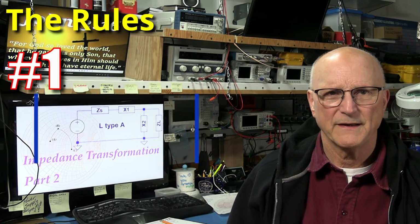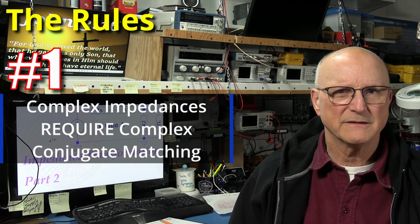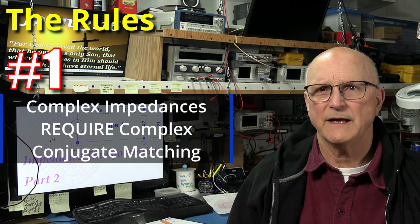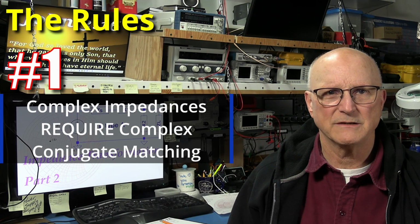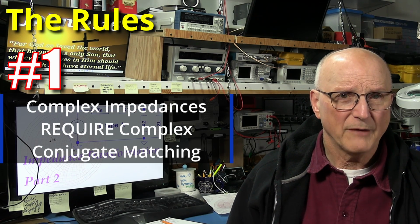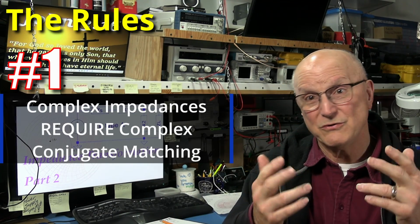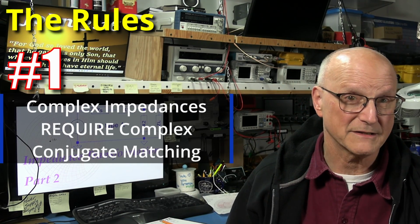Rule number 1. If either of the impedances are a complex impedance, then you must use a conjugate match with that impedance. If both are complex, then you get to choose which one of the two to use as your conjugate for the process.